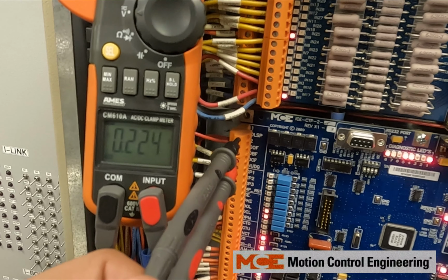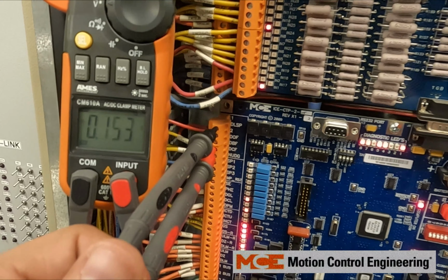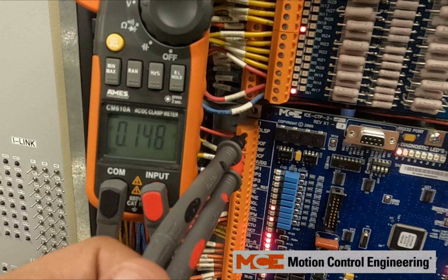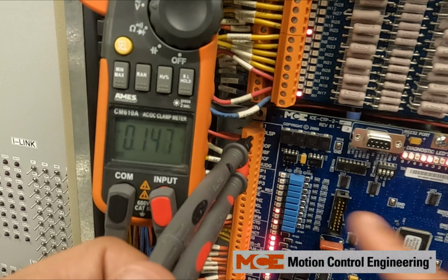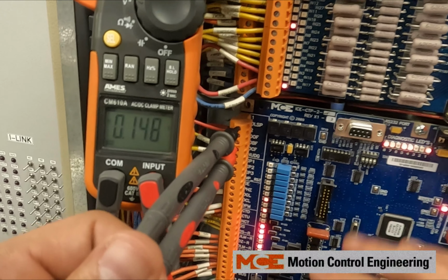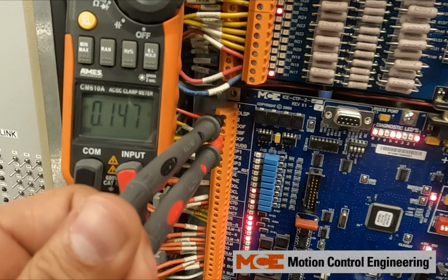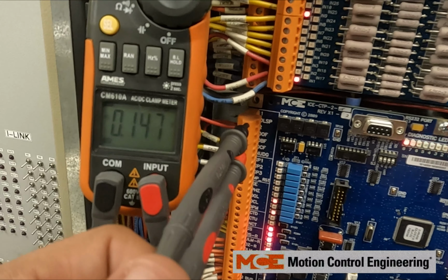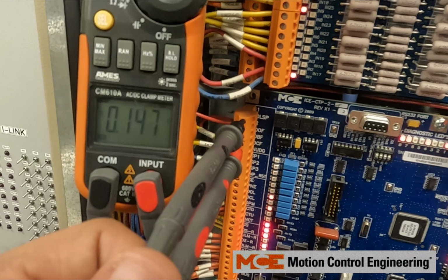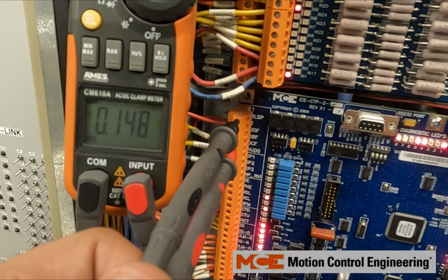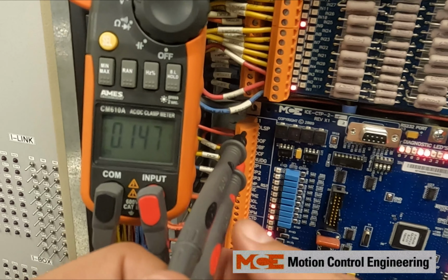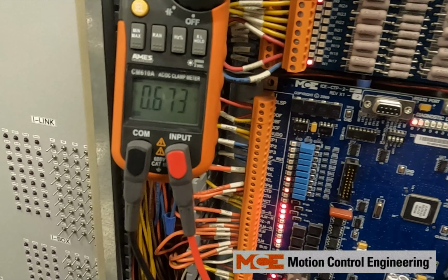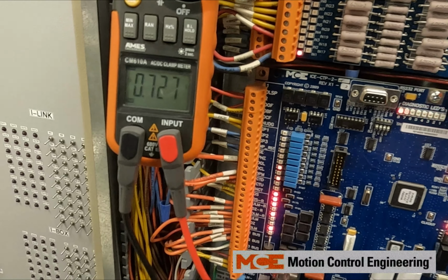If you see the software saying door open function, but you're not getting the 120 volts AC out of the car top board, it means an issue with the car top board. If you are getting your proper voltage out of the car top board, but the door is not opening, then it's something to do with the door operator side. You could also test your door close function and your nudging on here.